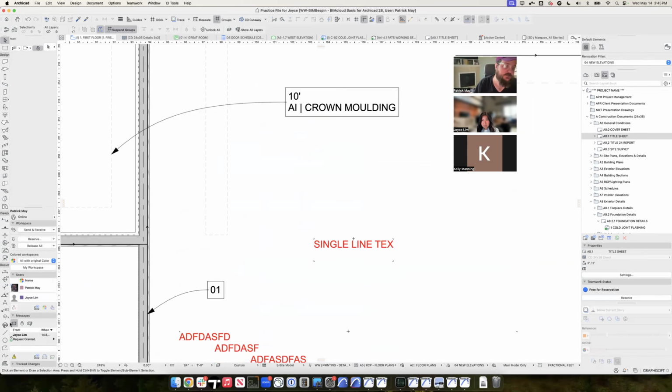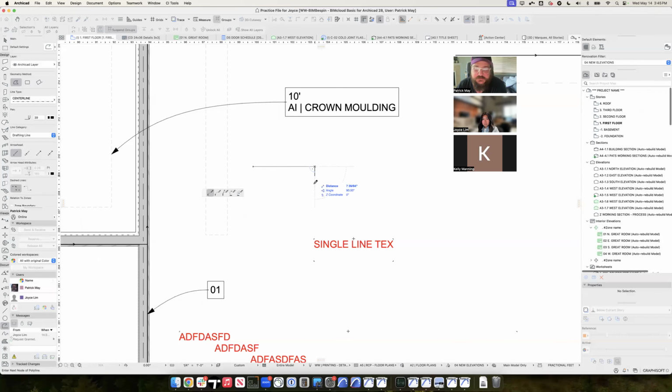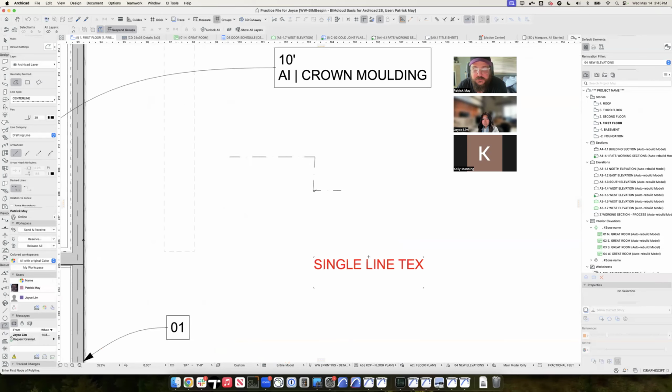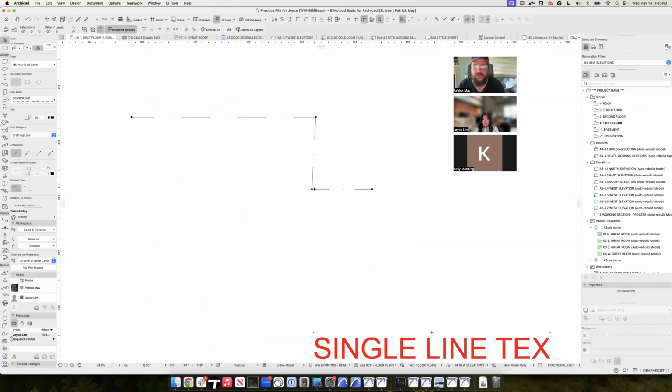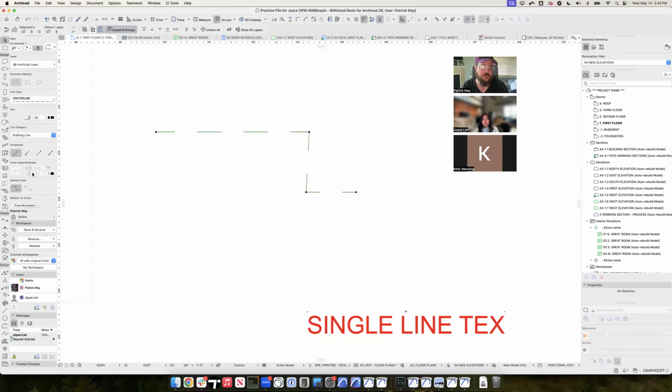All right, the line, circle, polyline, and spline tools. I mean, these are just drafting tools. They have arrow options for dashed lines on the polyline. They have options for how they interact with the corners. So the cool thing about that is that if we draw a line, it's never going to leave a blank at that corner unless it's using this other type, and then it's just going to carry the length of that around. But generally speaking, that dashed line type is what we want to use.